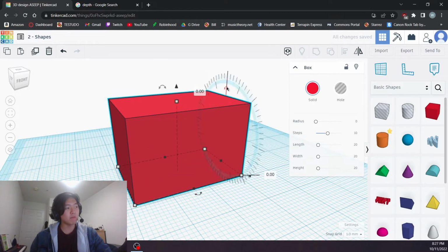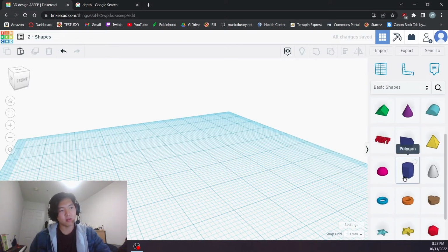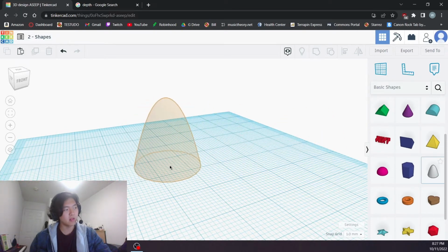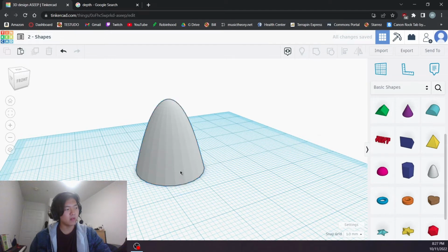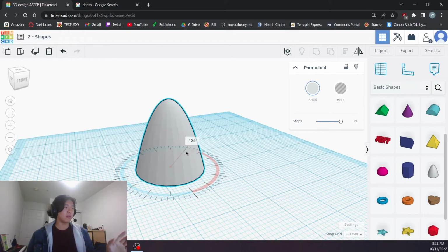Now these guys here allow you to rotate. I think a cone, actually, let's get something that'll be sure. I think this won't be bad. All right, so click the shape, click this, and now you can drag. If I'm inside the circle, following the bigger grid ticks, it will snap in increments of 22.5, which is pretty nice.